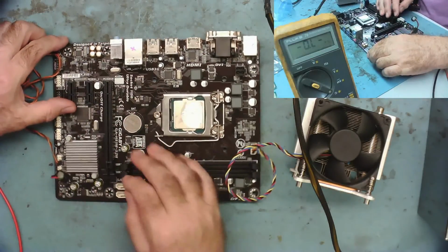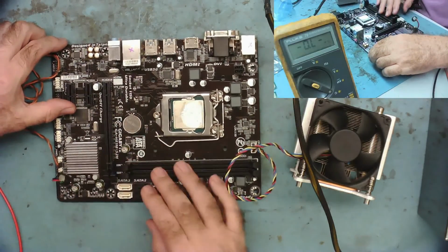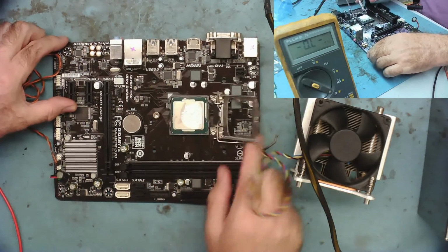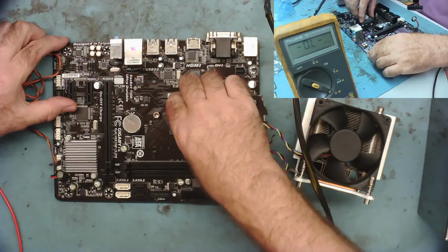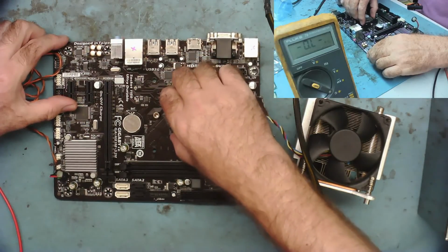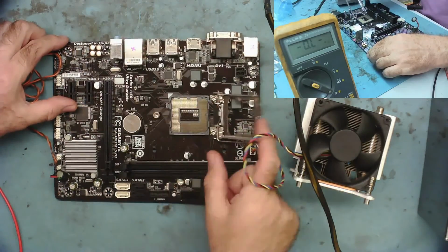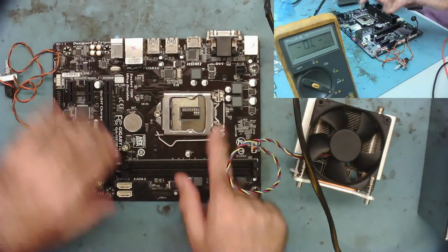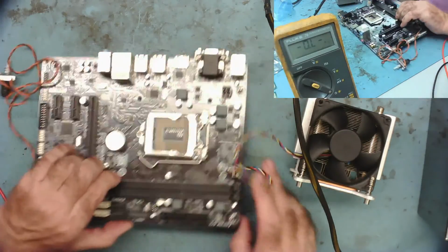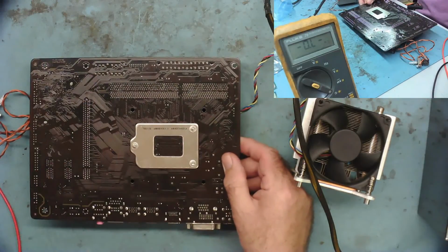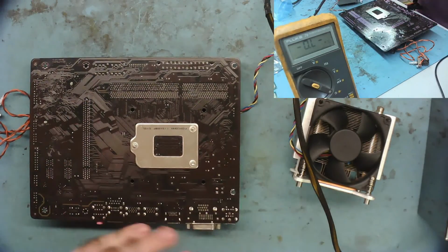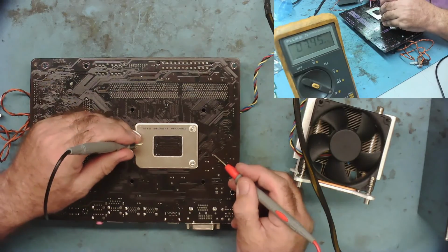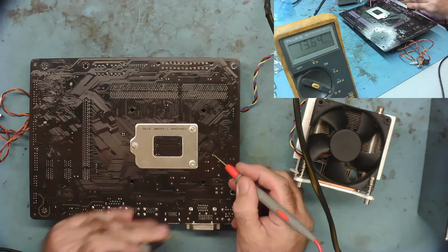Somewhere in the logic, the PCH almost certainly is sending the signal. I guess we could just check V-core, because I think this wasn't getting out at all. So we take the CPU out, because that will be quite a low resistance, and then we can flick the board over and have a look to see what's on V-core to ground. So we go over here. Let's have a quick look at what we've got. From the inductor coils which are here to ground, I'm guessing that's a good ground.